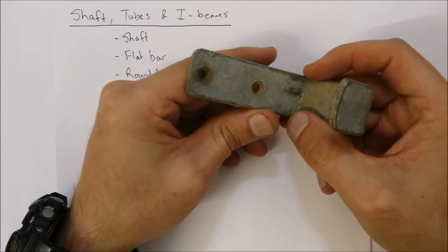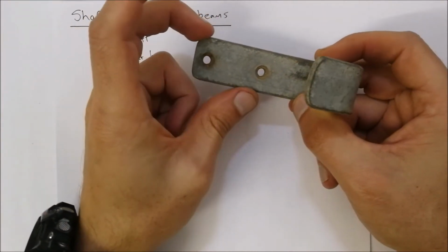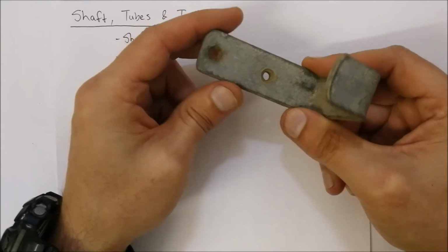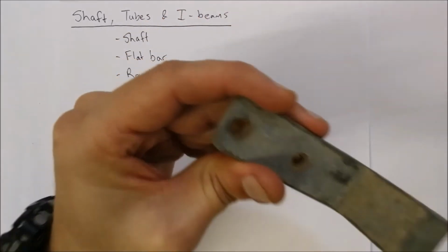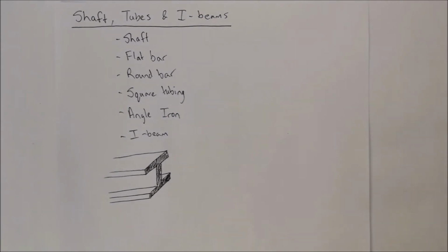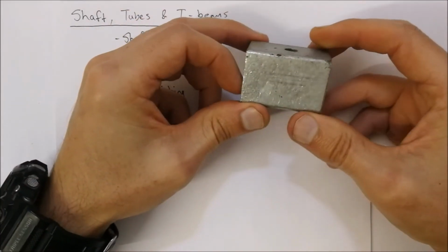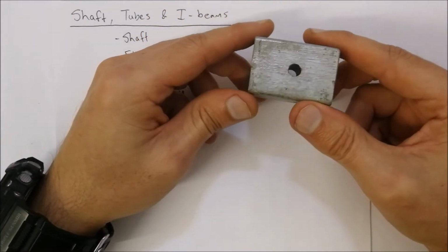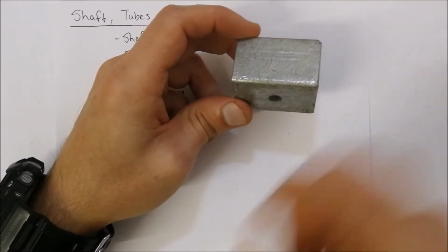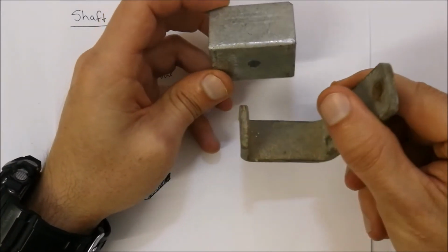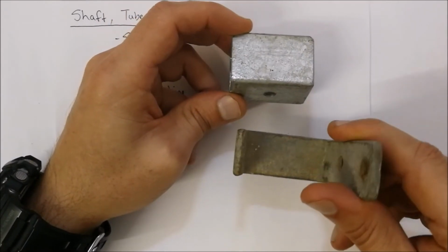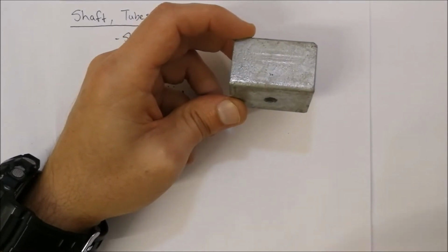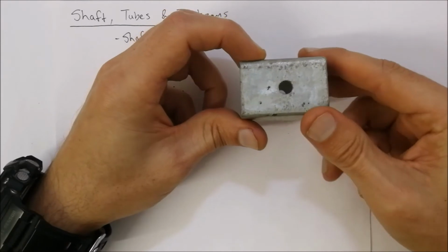and so therefore if you have your mild steel, which is prone to corrosion, covered up with this zinc layer, it's going to protect it from corroding that easily. And I've got over here also a piece of material that has been galvanized, or the zinc layer has been placed on it more recently, so you'll be able to see it's shinier compared to this one, which obviously has a little bit of corrosion on it, where the zinc has formed some oxide layer, not corroded away though, but it's formed an oxide layer,